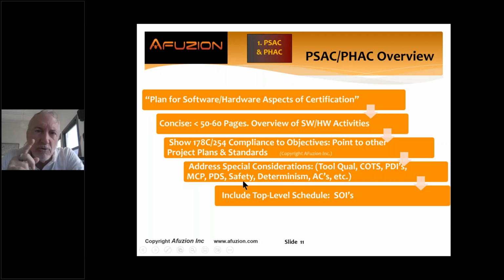And then safety, increasingly important. Are we applying 4761 or 4761A? Ooh, what about the safety requirement attributes? Have we captured all of the FHA, the PSSA, the PSAC within safety requirements? Do I have any derived requirements? We're going to talk about that. Big mistake in PSACs and PHACs, not addressing derived requirements. And folks, please don't tell us you don't have any derived requirements. All your requirements have parent requirements. Let me show you why they don't in about 10 minutes.